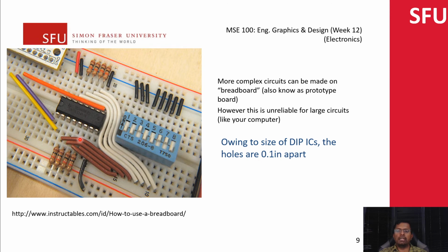These are known as DIP components, dual inline pin. So this is an integrated circuit. I'll quickly go over what an IC is in just a little bit. But nonetheless, what's happening here is that this distance is going to be 0.1 inch, so that you can actually fit it inside the breadboard.